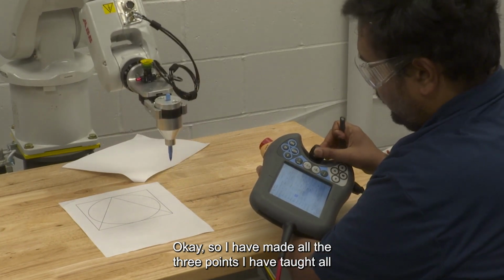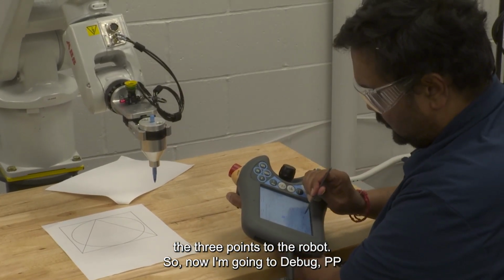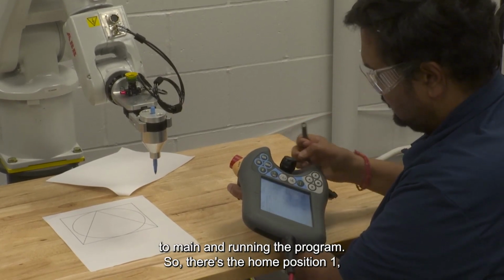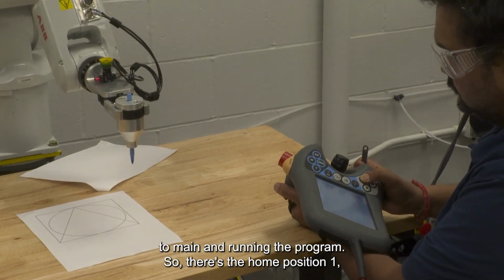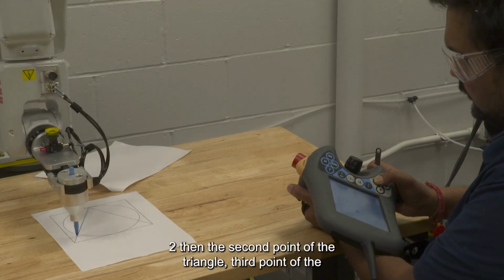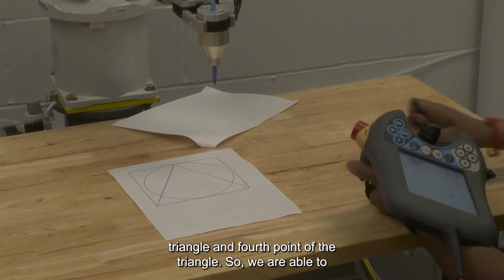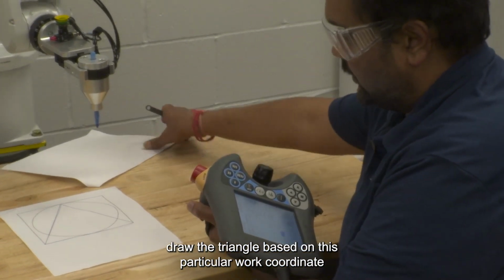I have made all the 3 points. I have taught all the 3 points to the robot. So, now I am going to debug, PP to main, and I am running the program. So, that is the home position, 1, 2, then the second point of the triangle, third point of the triangle, and fourth point of the triangle. So, we are able to draw the triangle based on this particular work coordinate system.